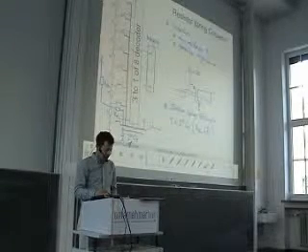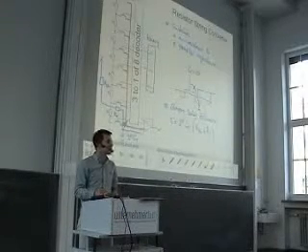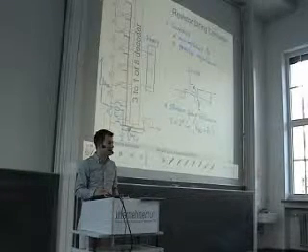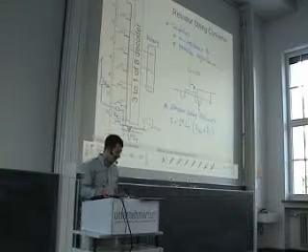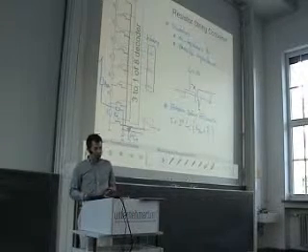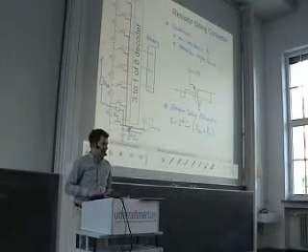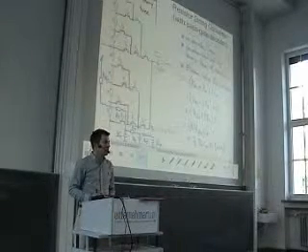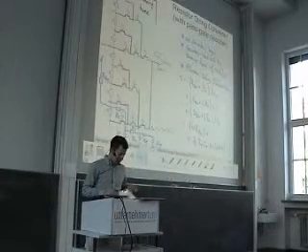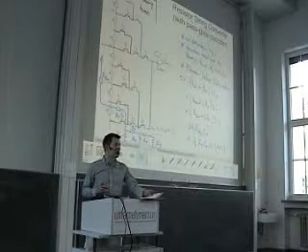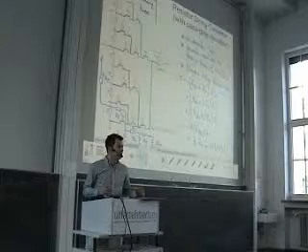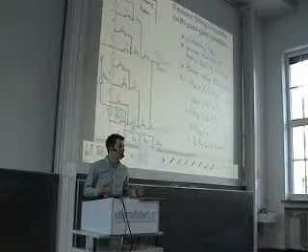So for a higher number of bits, the speed advantage of this architecture is reversed, and this architecture may become even slower. However, this type of DAC, either this one or this one, is usually used for a small or medium number of bits. So this is not the architecture of choice if you want to achieve a high number of bits.